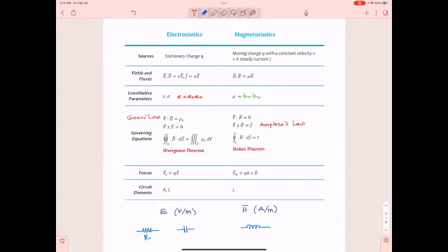So practically, you take a very complex structure, and then you identify one symbol to represent it. These are two-port structures. If you have three-port, you may see something like this. That's a transistor. By doing this, we can leave this extremely dense complexity and go to something simpler, and that's how we solve problems.